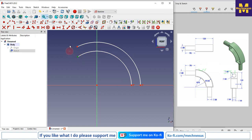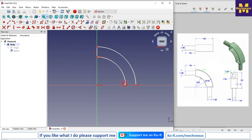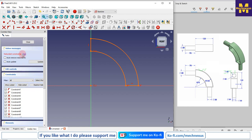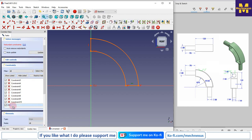So I will join these two points with a line, and I will make it vertical, and I will also make this line vertical. Same I will join here, and I will remove the conflict. I will delete the constraint 11. So now our arcs are concentric.